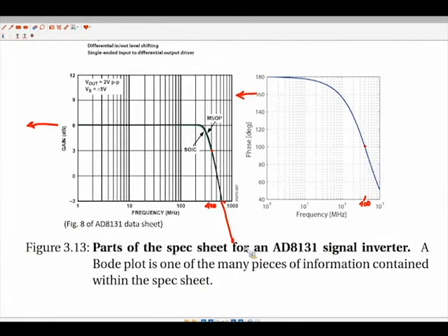That's going to be attenuating that signal. As we try to increase the frequency of that signal even more, the gain is going to be even less. So we're having diminishing returns as we go up and up in frequency. So the bandwidth gives an idea of what range the system is operable, where we are actually going to have the performance that is expected, or what it was designed to do.